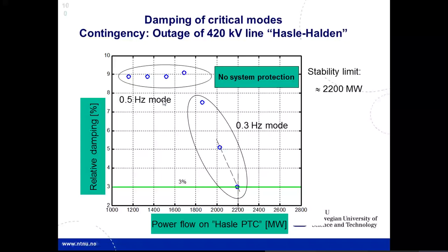There is excitation of another set of modes, and it is of 0.3 hertz with a very poor damping factor. So if we recall the example from the Kundur book, we had one case of 50 megawatt, another case of 400 megawatt. And thus, for the different operating conditions in the line, the mode property, and thus the system behavior, the generator behavior has changed. And this is the real example you have here.